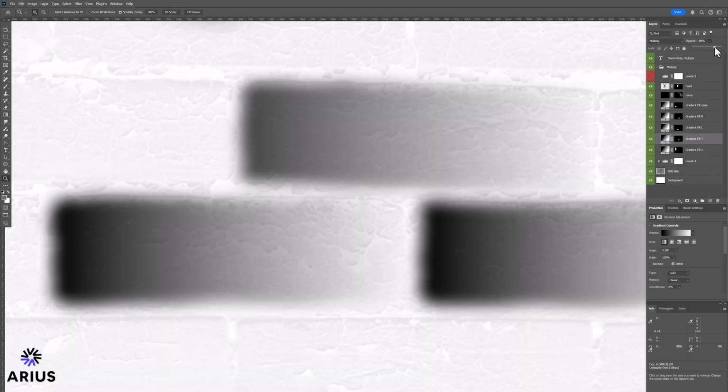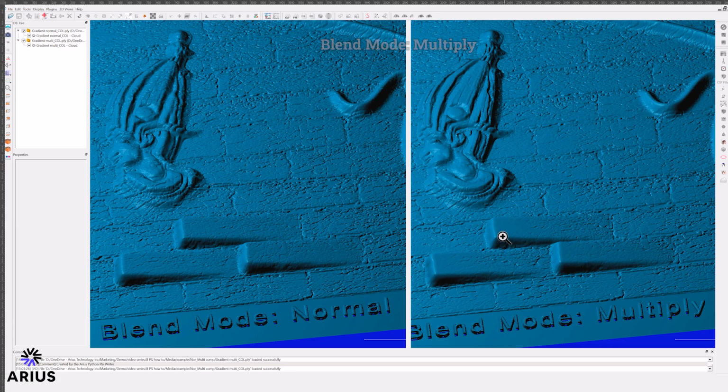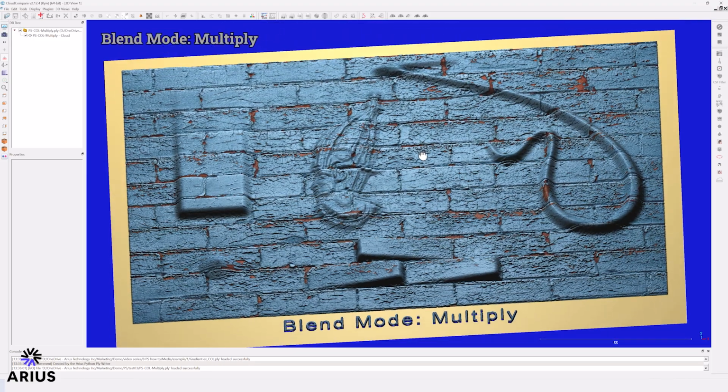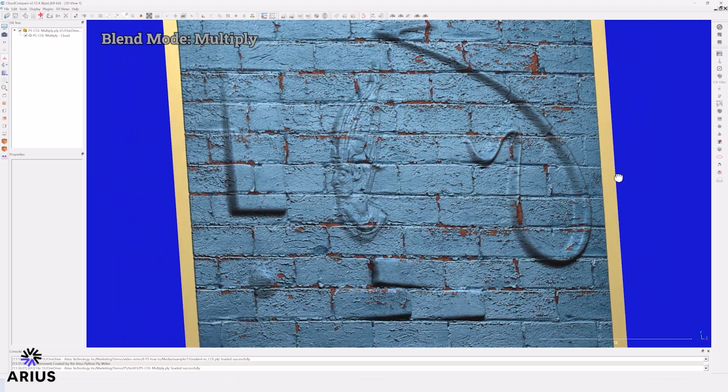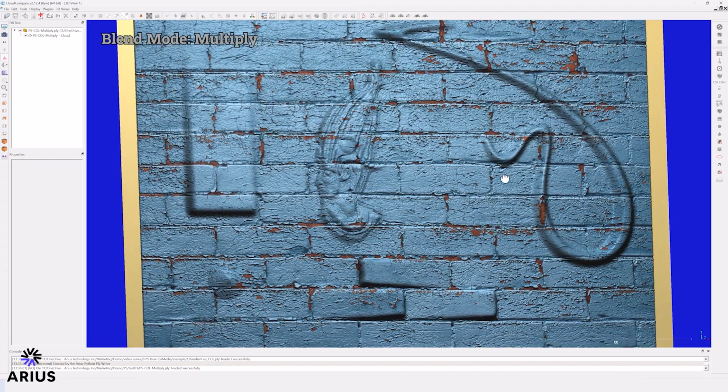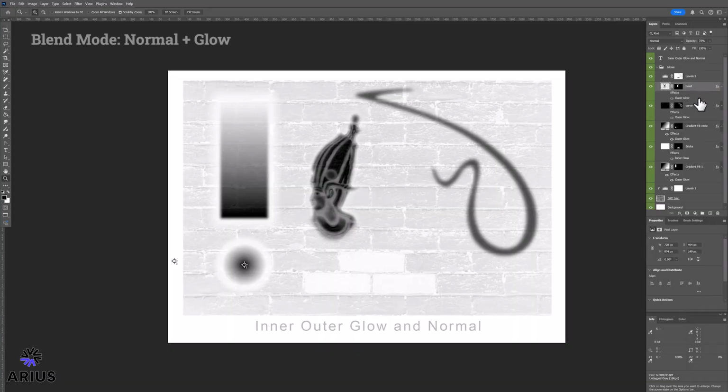This can be added back in by adjusting the opacity of the layer to restore some of the detail in the darkest areas as needed. Here, it's subtle but clear that the cracked paint is less intense in the dark portion on the multiply example versus the normal. It's all about the effect needed. So, as we've seen, layer blend modes can isolate an effect or target certain areas without having to paint customized adjustments. Care is needed to avoid unwanted walls being generated with any process.